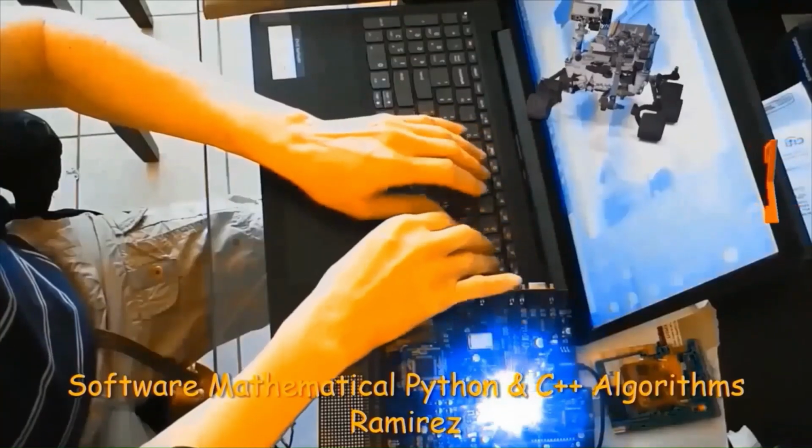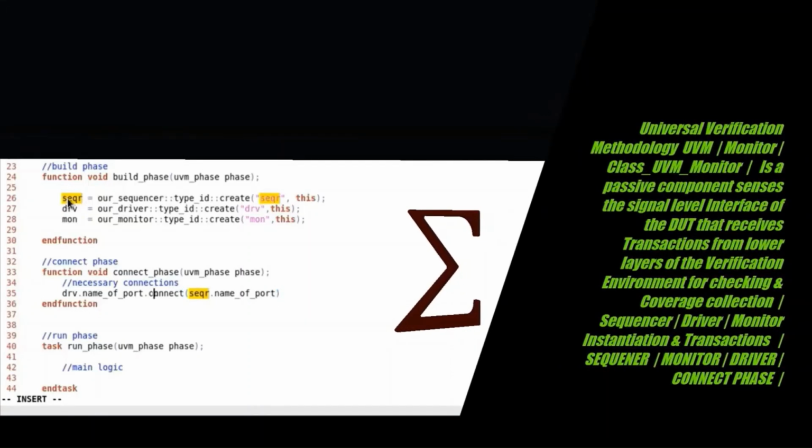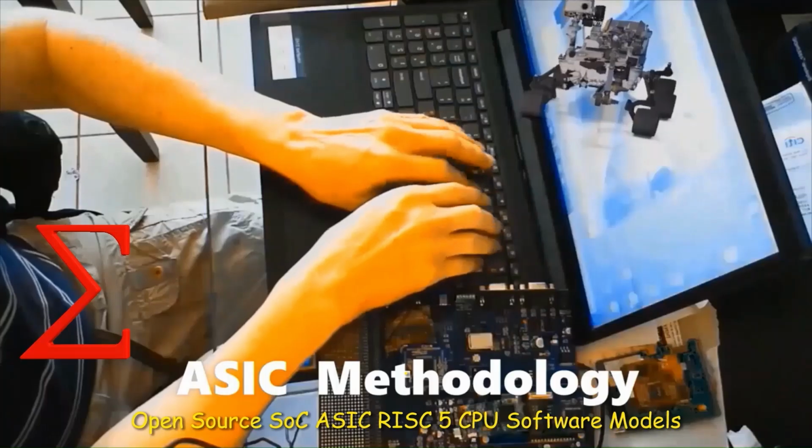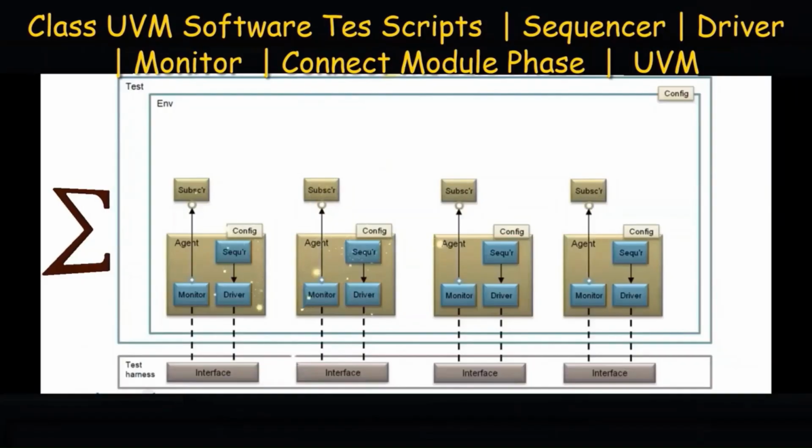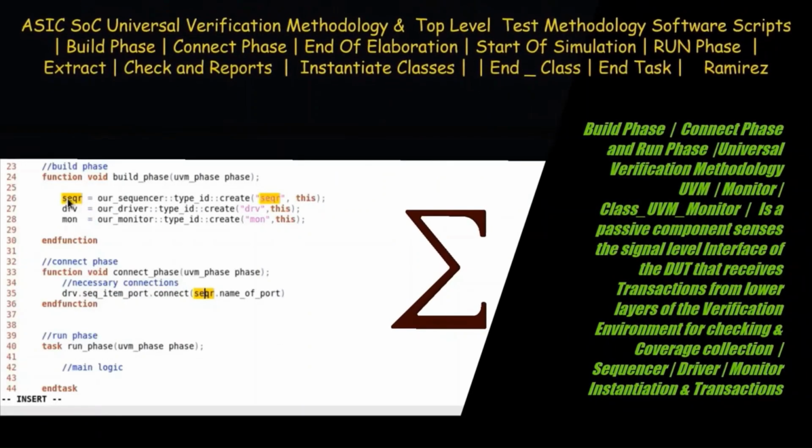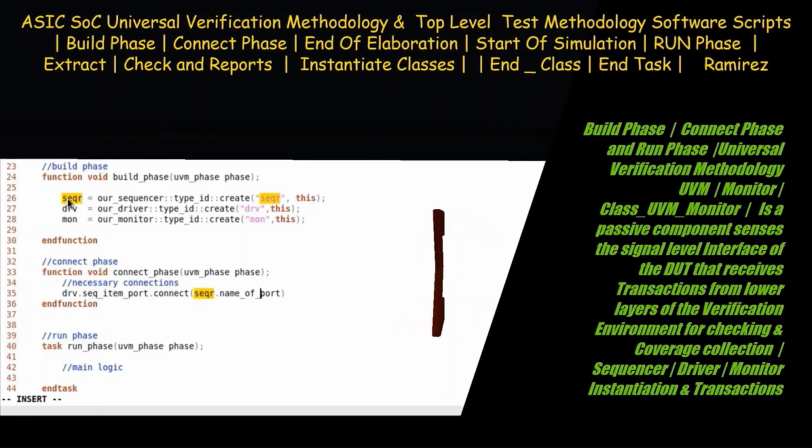The UVM code generator interface template file contains settings to include various user-defined code fragments required to define the UVM driver, such as the proxy or wrapper for the full driver transactor, much of which is implemented on the HDL side in the synthesizable bus functional model, BFM.